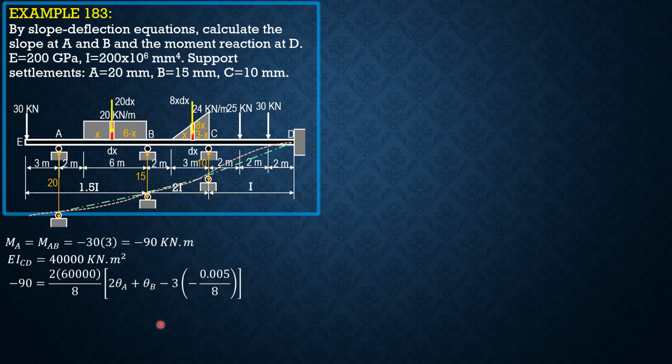Simplifying, plus fixed moment near A, it is negative, as A is on the left, so it is equal to the integral from 0 to 6 of 20 dx. A is 2 plus x, while B is 6 minus x, so quantity square over L square, 8 square. So negative integral 0 to 6 of 20 dx times quantity 2 plus x, 6 minus x square over 8 square.